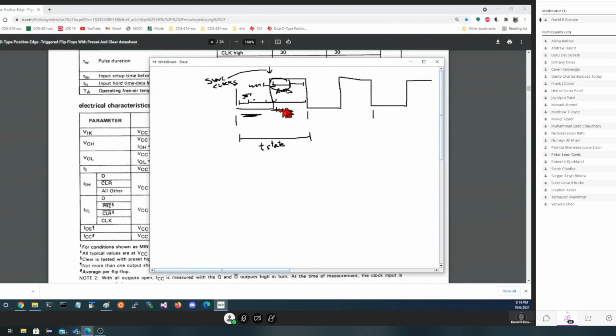But it can change any other time; the signals we need and the transferred data will remain steady throughout this entire high time. That way, if somebody wants to look at it and ask what the value is, they know only to look when the clock is high, and only after the setup time for the data they want to look at. And we'll work on that because that becomes critical to designing a processor that knows exactly where data is, and when it's valid and when it's not valid.